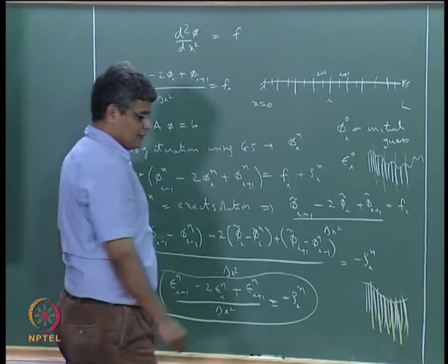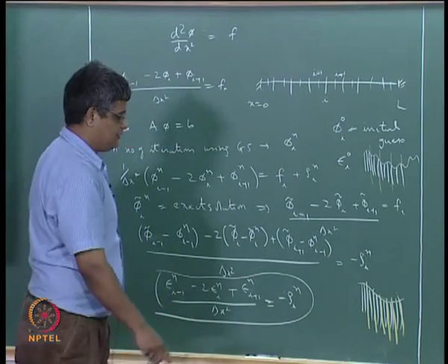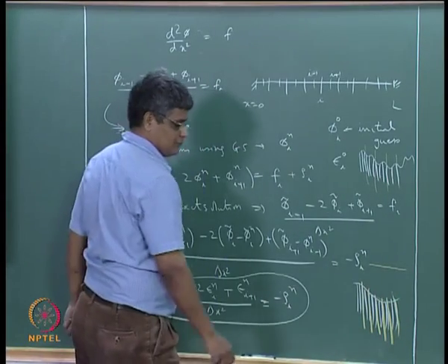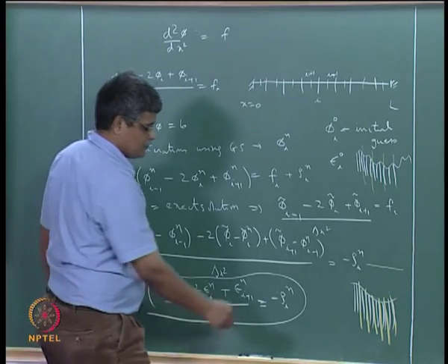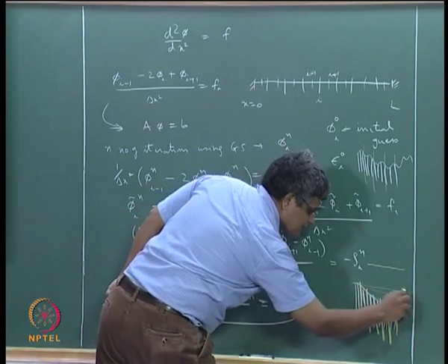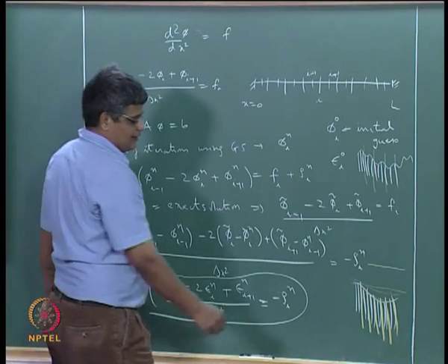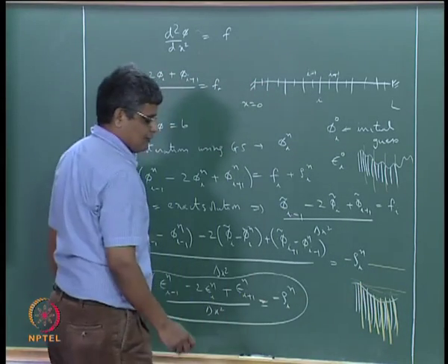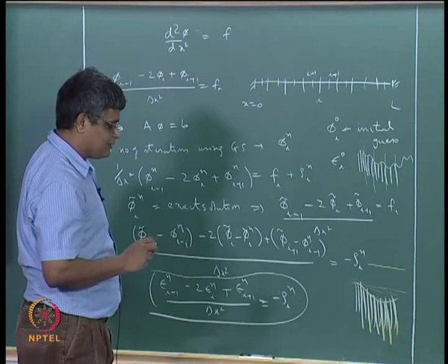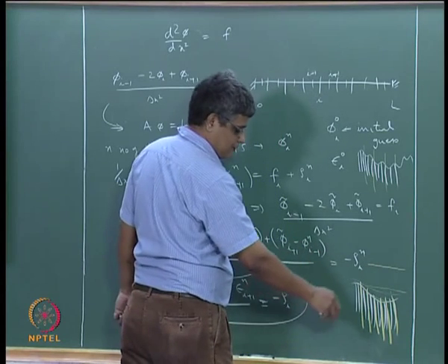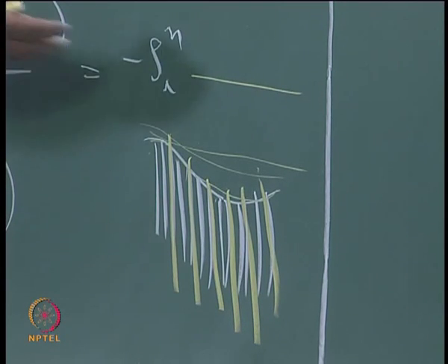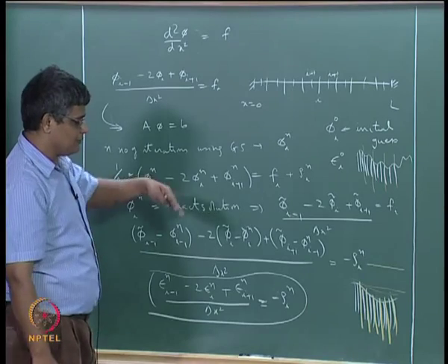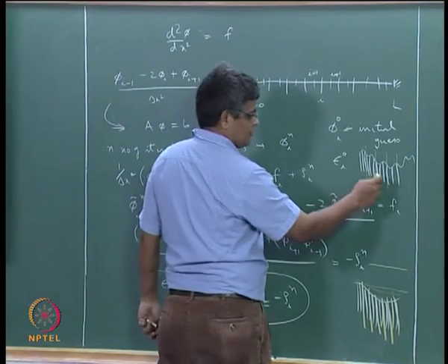Now what I want to do is that I do not want to do further elimination of the error. Ultimately, when I have the exact solution, the error will be 0 and it will not vary with space. Okay, I want to go down from here into this and then finally onto the 0 level, but the point that I would like to say is that because I have a smooth variation I can represent this using fewer number of points with increased grid spacing, and then continue further reduction on this smaller number of grid points and reach the end distribution where error at all points is very low and almost equal to 0.